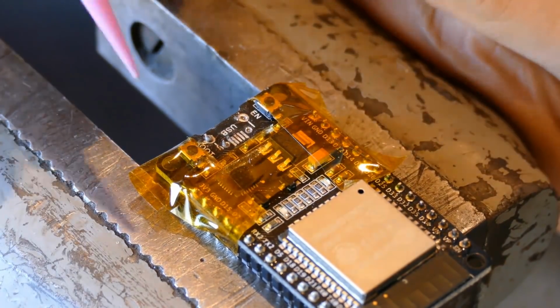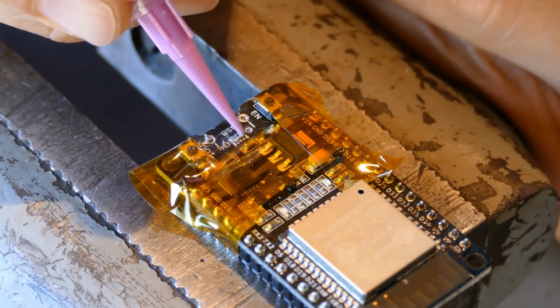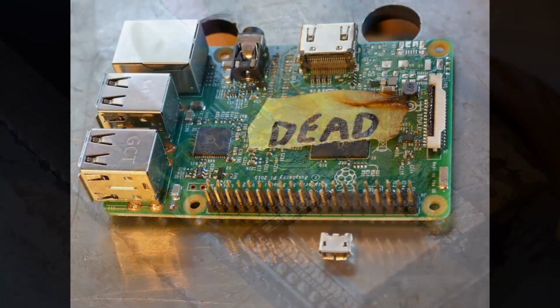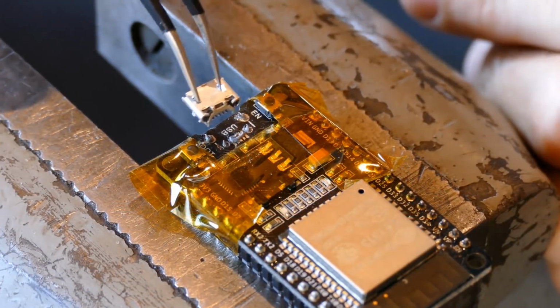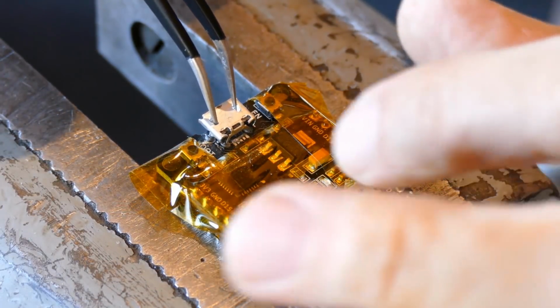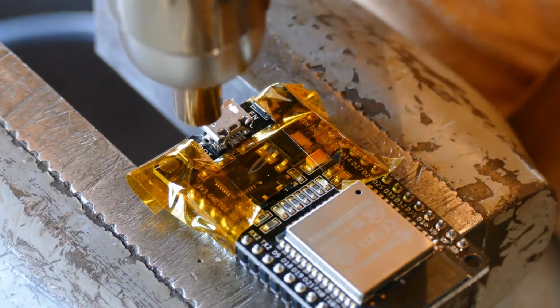The big through hole pads are a lot easier to apply the solder paste. Again, I'm applying way too much to the small surface mount pads. Off camera I removed a good micro USB jack from a fried Raspberry Pi that was beyond repair. The jack's back through-hole pins line up correctly, but unfortunately the front pins are off, so I just bent them at 90-degree angles and I'll surface mount solder them.